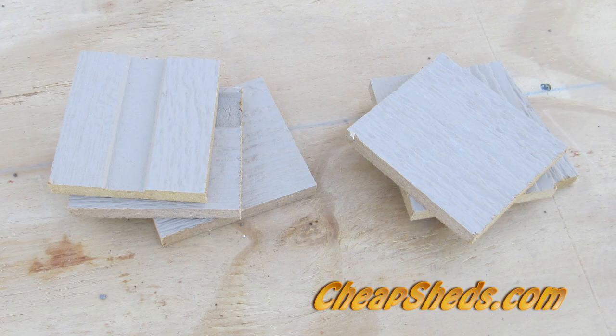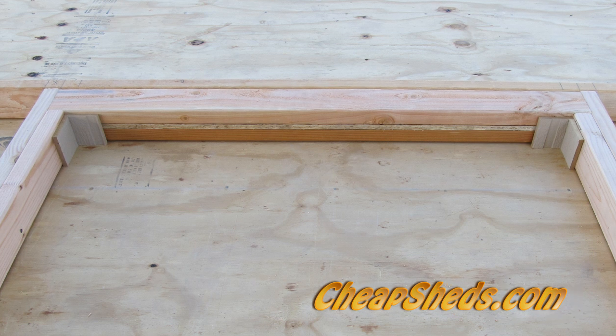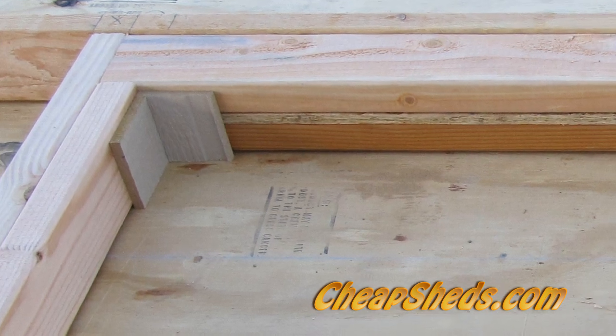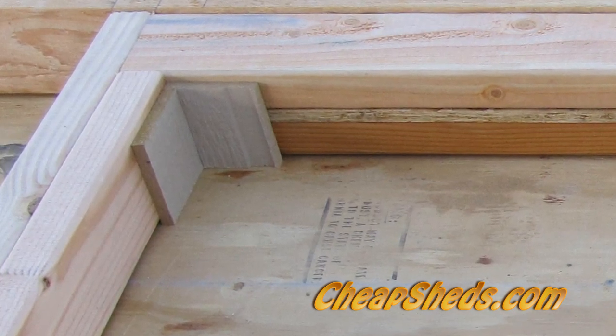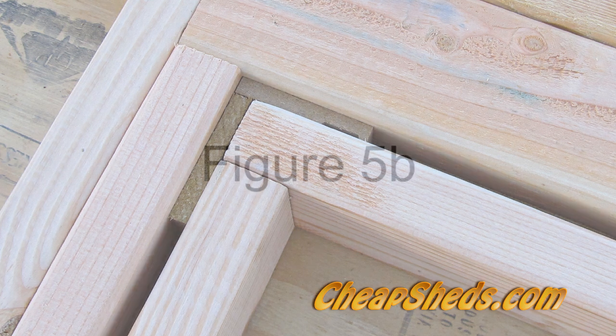Cut 8 3x3 spacers from the scraps of siding you trimmed from the gable end. Put the spacers loosely inside the outer frame, 2 into both top corners and 2 into both bottom corners. These are to keep the inside door frame from shifting until you get it nailed to the siding.